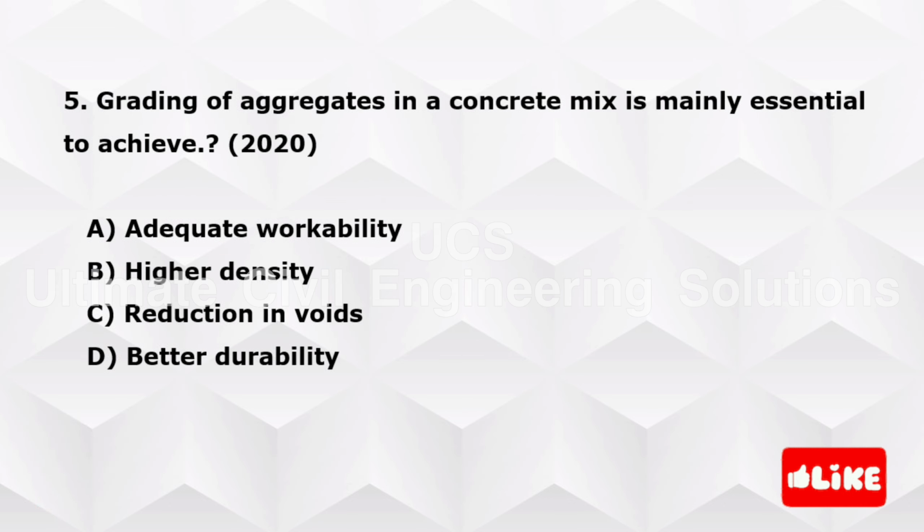Next question: grading of aggregates in a concrete mix is mainly essential to achieve. Options are: option A, adequate workability, option B, higher density, option C, reduction in voids, option D, better durability. Answer is option C, reduction in voids.